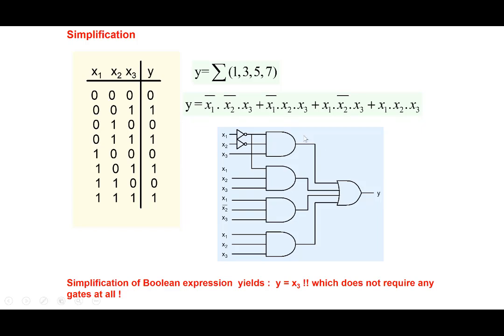And not only that, when you have more circuits, you can also think of each one of those pieces of circuits, they also dissipate power. So when you're switching some inputs, the capacitances have to be charged, discharged, and the switches are not ideal, they have resistance in them, and so power is dissipated. And so when you have a more complicated circuit, you have more power dissipated also.